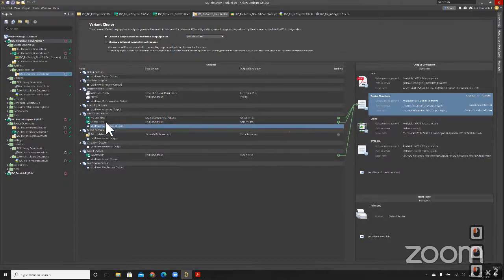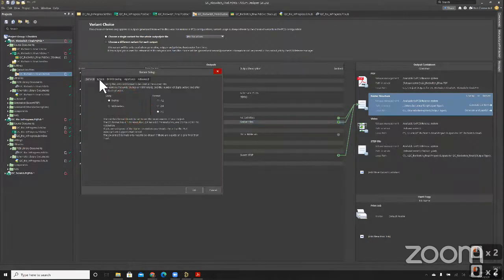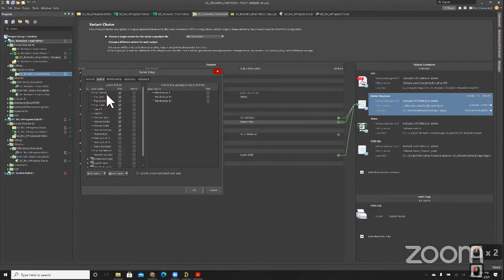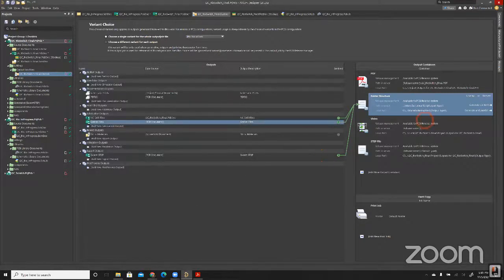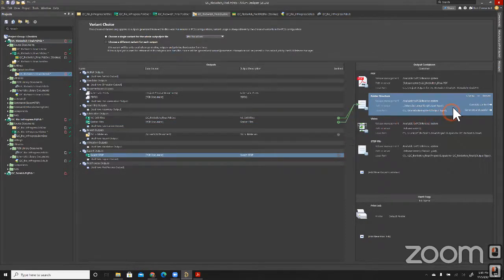And so when you do those things, you'd double click on your Gerber setup, go into your layers and select all the different layers that you want to actually go and manufacture. So the top overlay, the top solder, top layer, layer 1 and 2, which are the 2 that are sandwiched in between, the bottom layer, all that other stuff. You actually probably don't need the top paste and bottom paste, but I'm just leaving it there. And so when you do that and have those things pointed to the folder structure, I'm actually going to remove this step from it real quick.